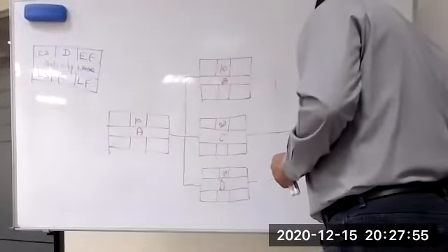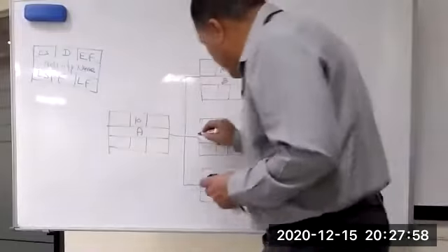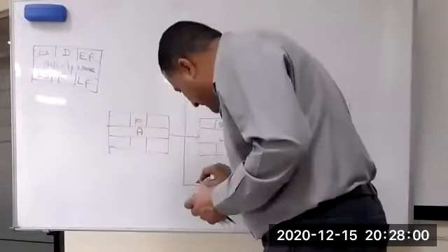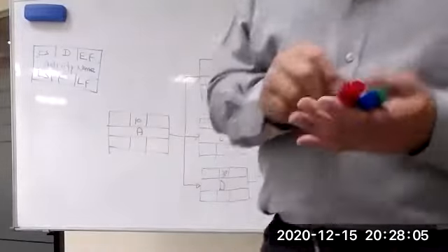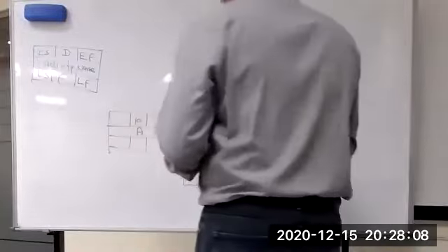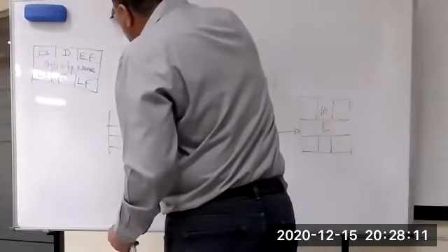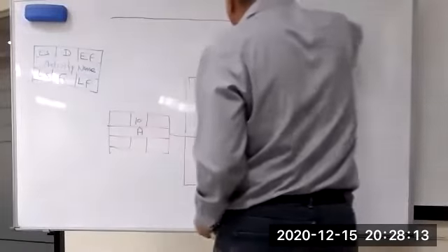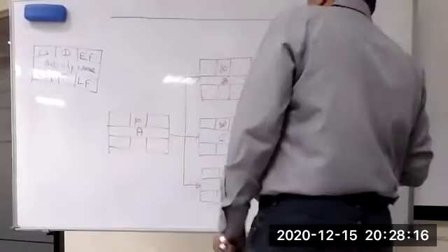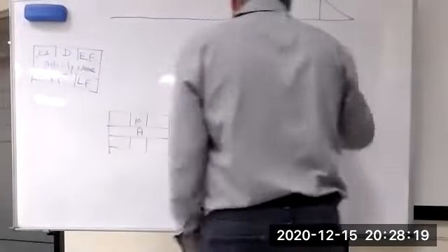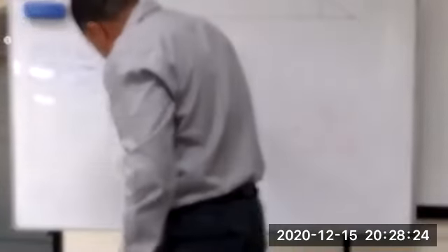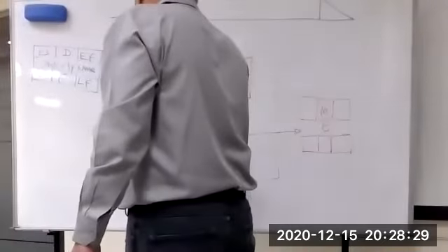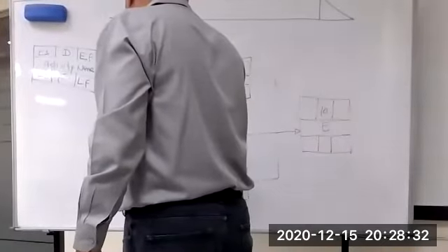What is the total duration? This is finish to start, in our exam, guys, finish to start. This network we call the precedence diagram method. How to calculate? We calculate in two directions. The first direction is from left to right, the forward pass. Always we start from the left. Here we start date, start date 0.